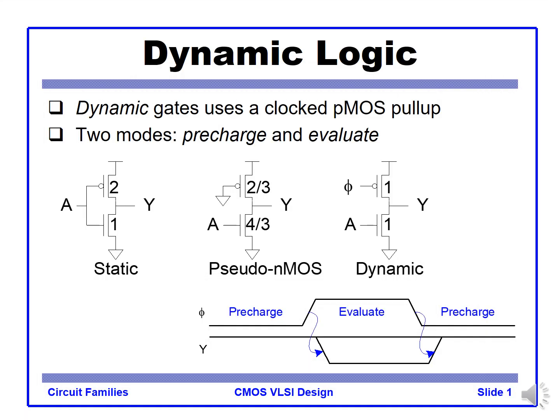So dynamic logic. We will see how we save the power from the pseudo MOS. We evolved from the static CMOS logic to pseudo MOS. By having that, we can reduce the input parasitic capacitance. It has the potential of a faster logic evaluation. But the problem is the PMOS device that is always on. So we made it temporarily enabled by having a clocked PMOS